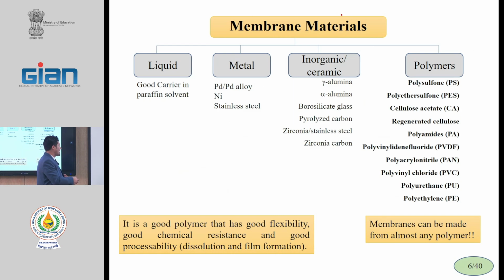And we need a high molecular weight for flexibility and chemical resistance. And in most fabrication processes, the polymers need to dissolve in solvent. We must first dissolve the polymers in good solvents and next prepare the membranes. In most cases, the synthesized polymers do not have good solubility and we cannot use them. Therefore, we must change the properties of polymers for good processability and dissolving.